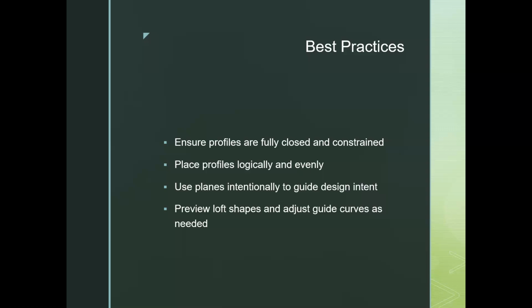Okay, always create your planes, understand what you're trying to create, and things of that nature. And that's what it's trying to discuss here by use your planes intentionally. So just depending on what you want to create, you're going to set it up that way. And all of them should give you a preview of how the Loft is going to be. And if you need it to stiffen up, here's that one thing that's common amongst all of them: go ahead and use that guide curve, right? So remember, quick breakdown for it.